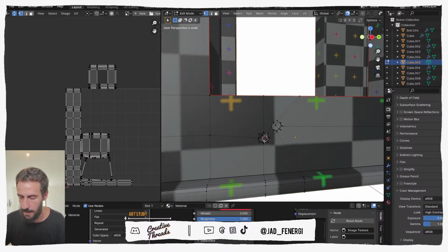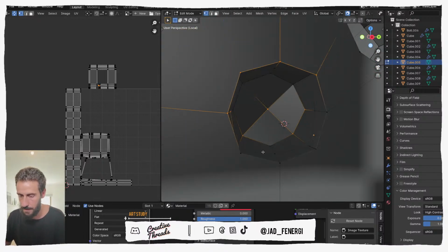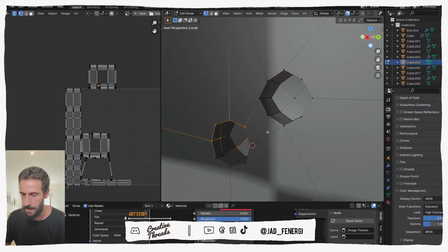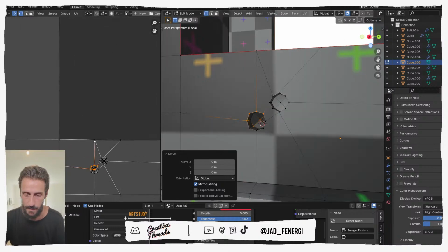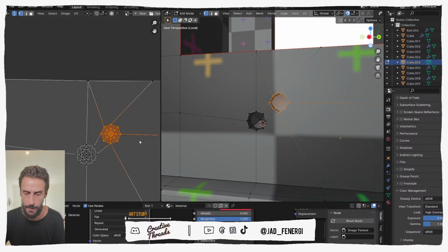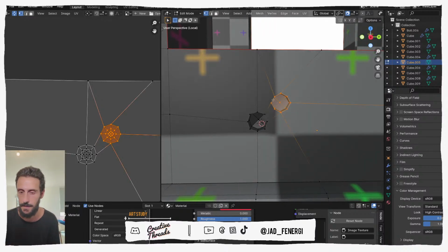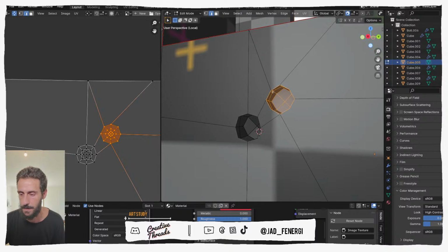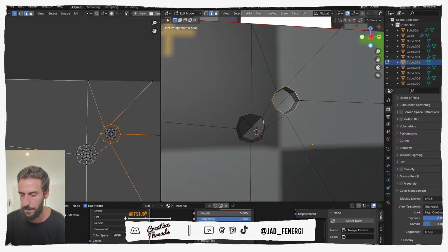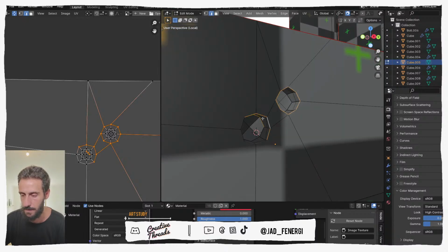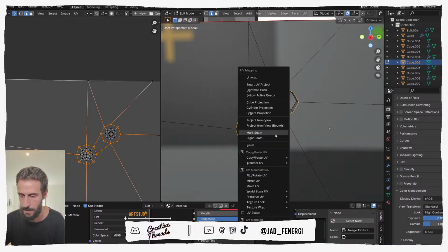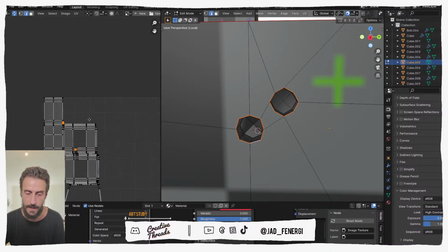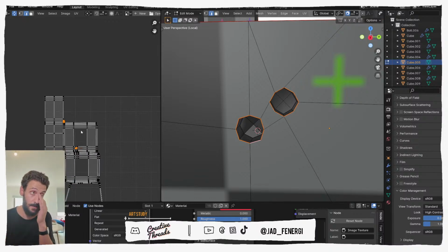Anyways, we were saying that here you can see that this is not wrapping properly. This is not the proper representation of this geometry if you want to flatten this out. So just for the sake of showing you, you can pick these edges. Although, in my practical use cases, I won't do this. I'll just keep it. That's fine. Having distortions here is not a big deal, so you can just press U and then mark a seam in here. Whenever you mark a seam, it unwraps everything. So this is something that you also have to consider.